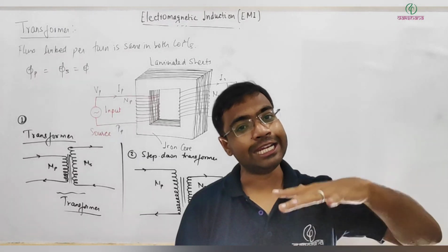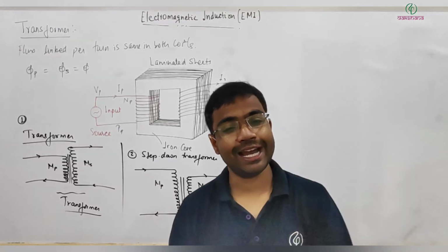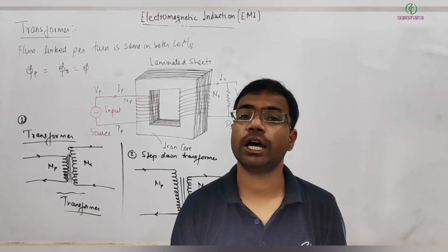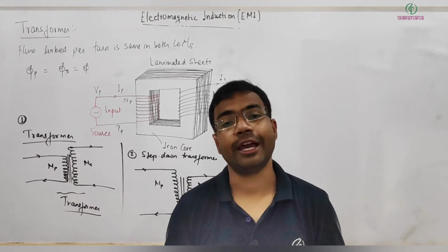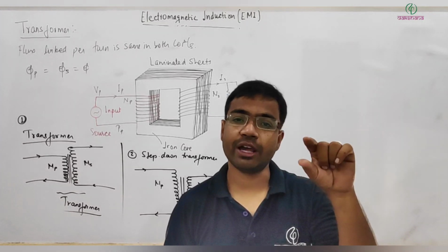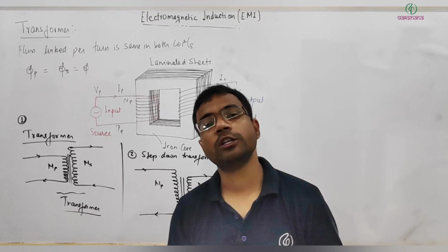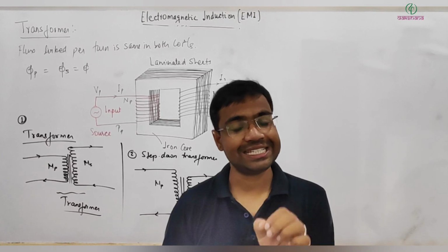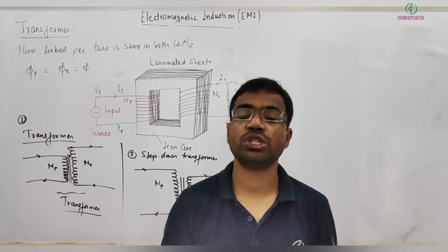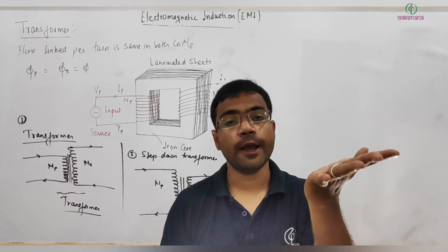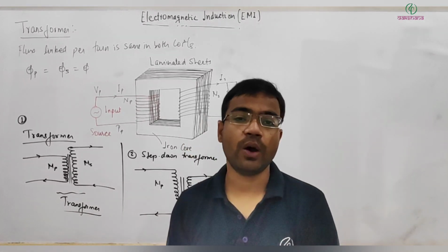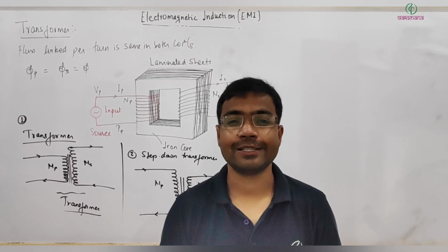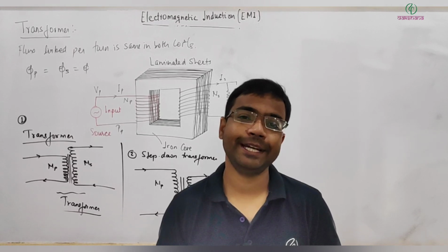But if we increase the voltage and reduce the current, the voltage difference increases but the current reduces, so the losses in the transmission lines will be I square R with a very small I. So I square becomes very small, and the overall loss is reduced by many factors. This way it is a must to use transformers, stepping up the power at the generator and stepping it down at the final destination. So I hope you understand why transformers are important and why they are required.